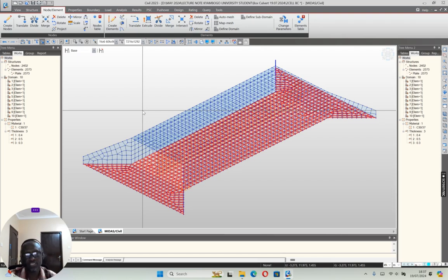Gentlemen, for soil structure interaction, the spring constant we apply, you can do other formula, you do the foundation design, but what personally I know, and maybe members can also add their voice, is that once you know the bearing pressure, and then you also know the allowable deformation, which we normally adopt as 20, and the bearing pressure, because we are using rock fill, we believe we shall enhance the capacity. We are not placing it on the weak soil. So once we enhance, then I assume that my bearing capacity is about 300 kPa, and my allowable deflection is about 20 millimeter.